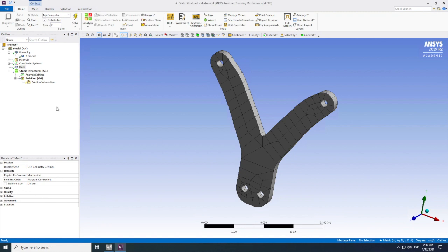So I think a lot of the power in Ansys relies on being able to control the mesh. For instance, I can select this edge in here, like that. I should keep the control button pressed. I go like that, one, boom. I'm gonna hit all of those edges.